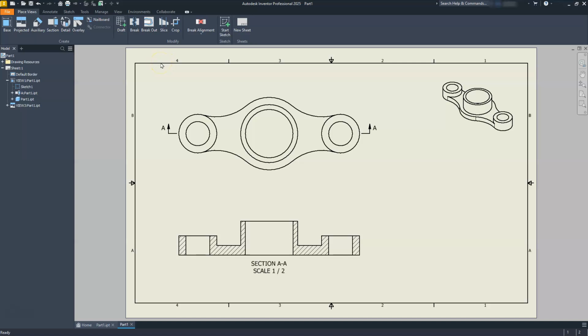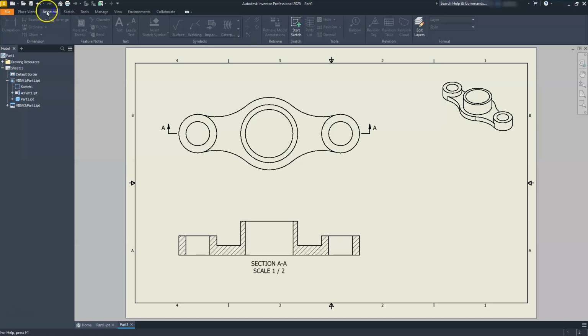I'll just do a few more things to this. This one is really simple to dimension, but I'll go ahead and put the center marks on here. So I'll just jump to the annotation, and then I want to find my center marks. Here's my pluses. Just going to select here and here, and let me maybe select here to get the center part on this one. And then with the center lines, I'll use the bisecting one here. And once again, this is just like we did in AutoCAD. The exact same steps, right?